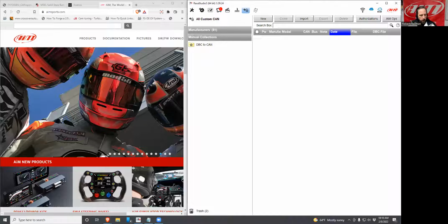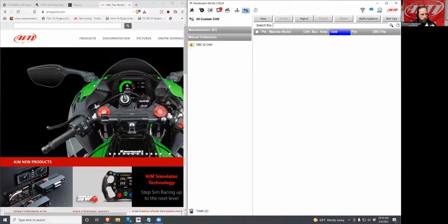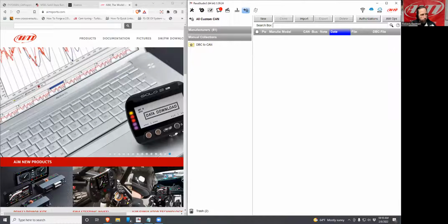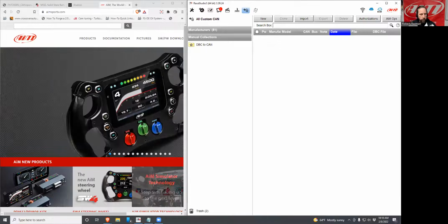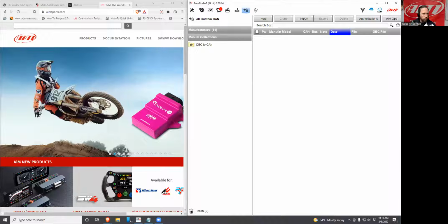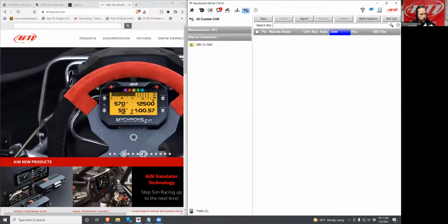So I have all of these things, and on paper, it seems like the PDM just doesn't have what it takes to get the job done. We have 3 CAN buses, 2 of which you can modify as end users, and 1 that is proprietary to our devices. That takes care of our GPS module, it takes care of our Smarty cams, and we are able to seamlessly integrate those without any type of configuration support. You just go in and say, I have a shift light module, I have a Lambda controller.